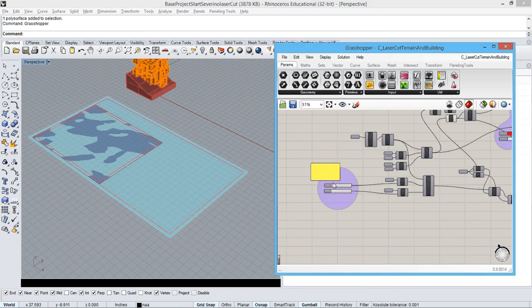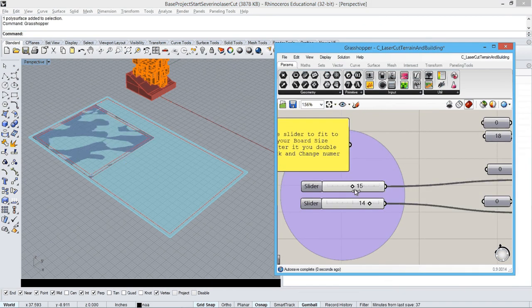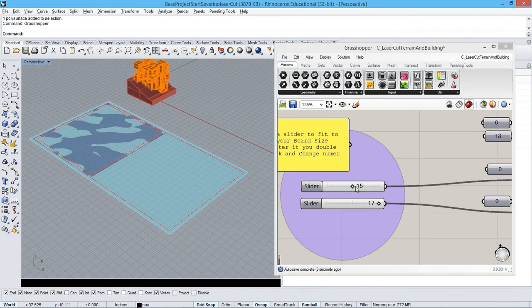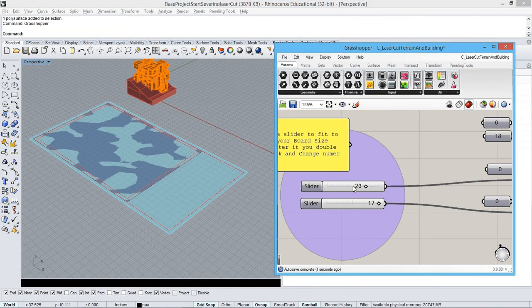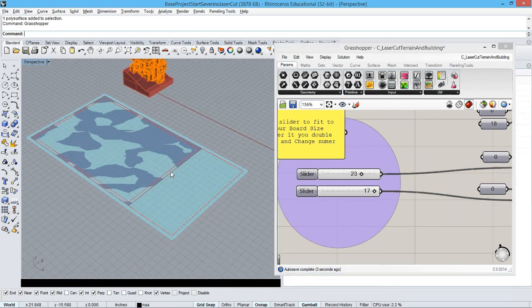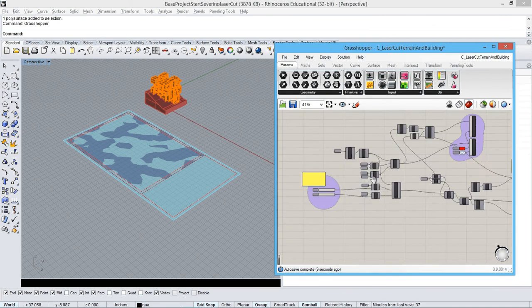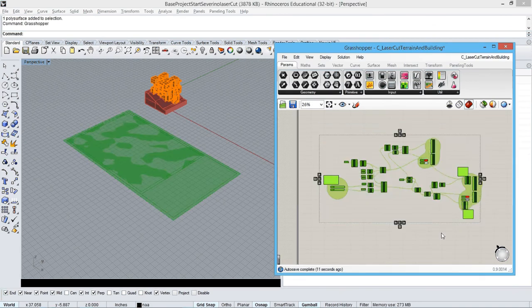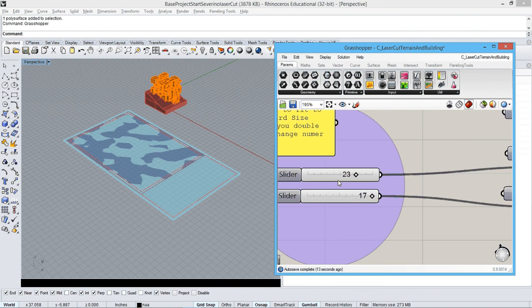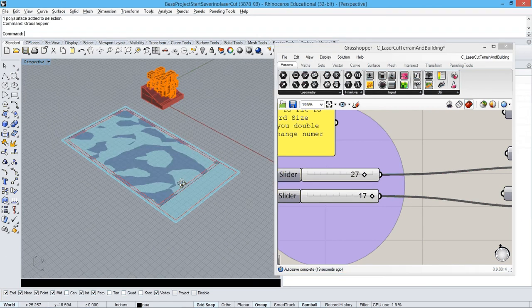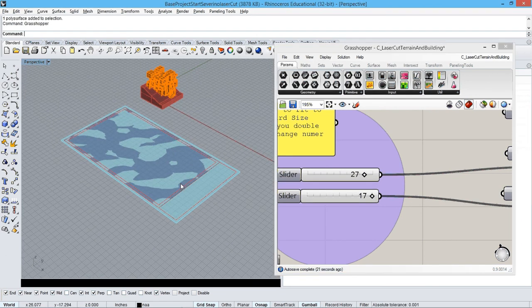Okay, so I'm giving some dimensions here that allow us to vary or change the dimensions of our board, but never, obviously, the board of the machine. That makes sense. So first step, the bottom definition, we set the dimensions of our material, our chipboard.